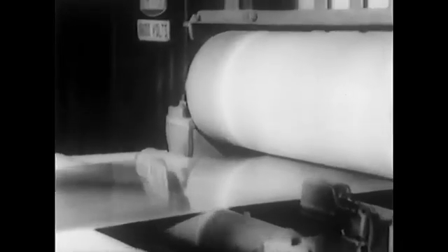The strip is raised to the top of the heater unit housing, inside of which is a series of high-frequency coils. As the strip comes down through these coils, induced electric current causes heat, which flows the tin almost instantaneously, greatly improving its structure as a protective covering.